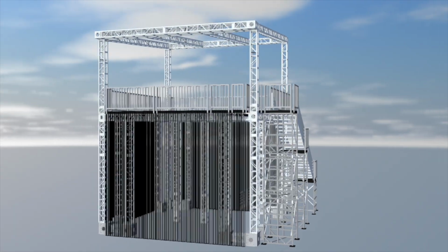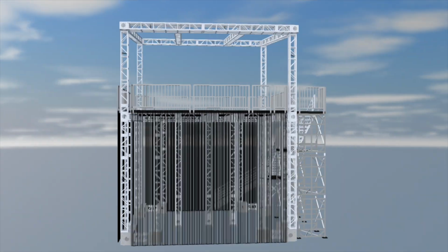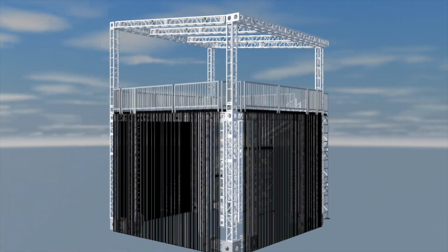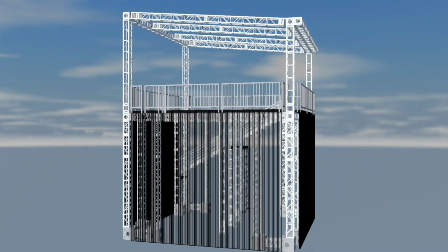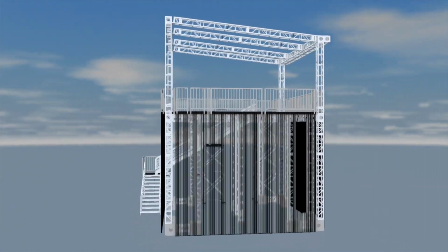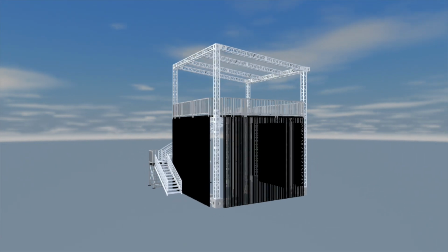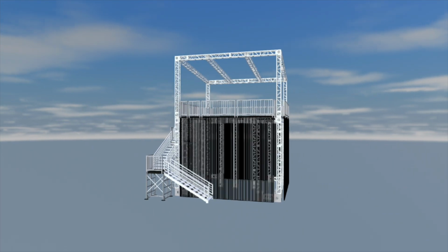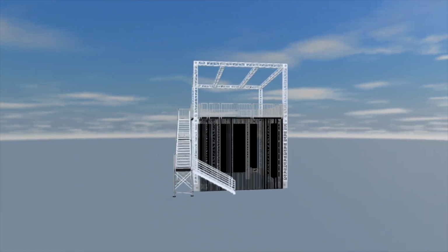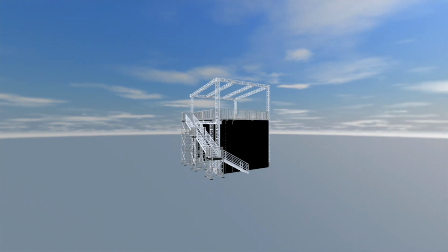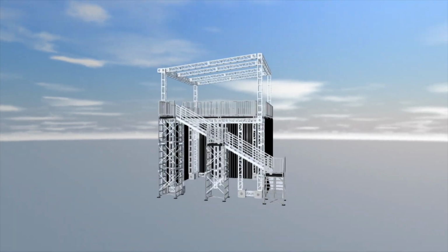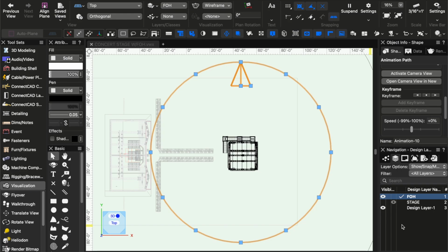All right, the render's complete. And that's truly what happens at front of house most of the time. You can see here in the rendering that we start with the default, and then we push out to 65 degrees wide by changing the keyframes. And then again, we push out to 90, showing you that by adjusting those keyframes in your view angle, you can get further or closer away from the object that you are doing the orbit path around. That's fine tuning, if you will.